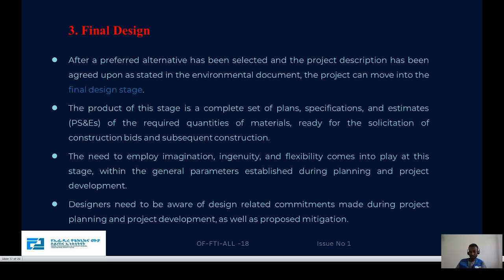It is a set of plans and specifications for the surface, base, and sub-base. The asphalt will have a specification, and we also estimate the costs and how much material will be required for asphalt, bases, and sub-bases. Any calculations will be done in the final design, and the horizontal and vertical alignment will also be designed.